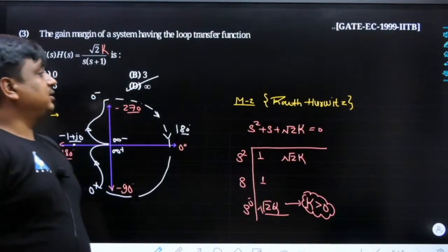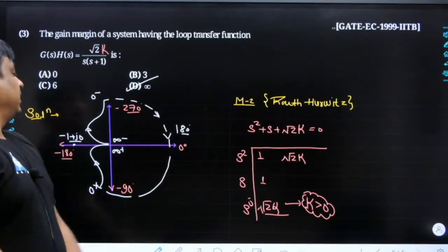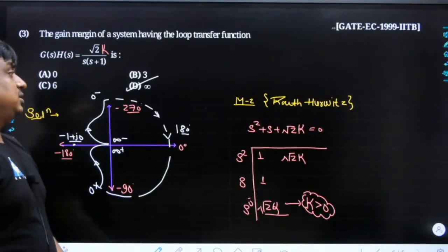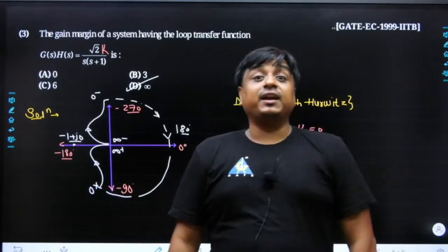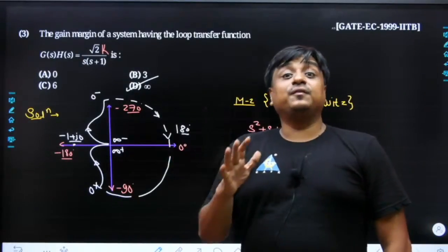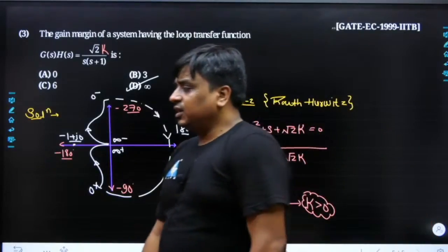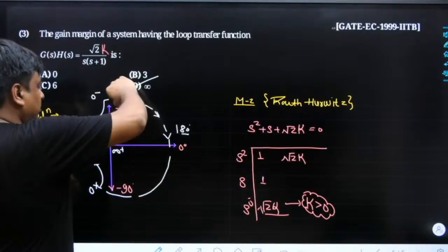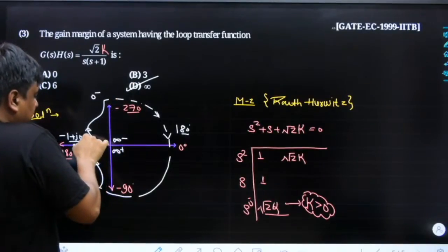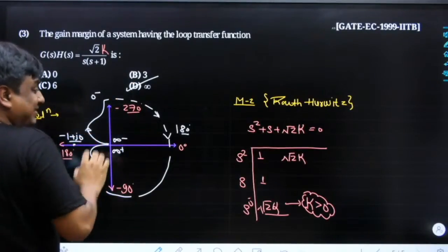But now, what are we going to do next? We had been talking about the phase margin. Because in this problem, we are going to have a finite phase margin, unlike the infinite gain margin. See why I am saying we are going to have a finite phase margin? Because in future, the lag in this system would be provided. After a certain lag, minus 1 plus j0 would start getting encircled.